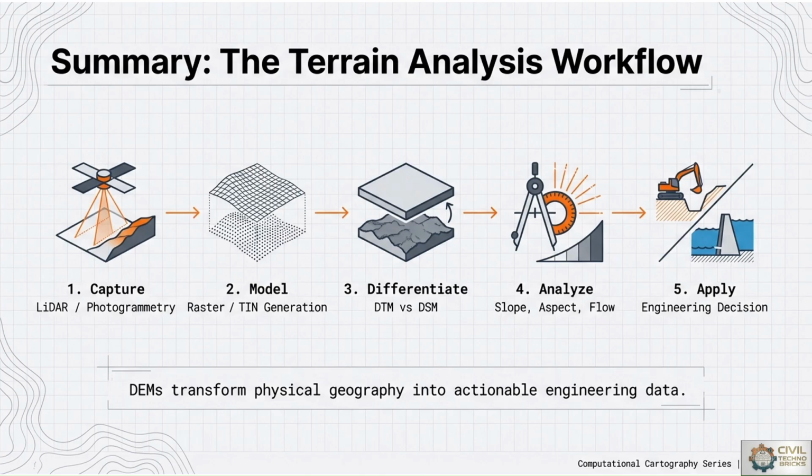The whole data is used as an input for the modeling, that is the raster data for TIN generation. The third step is the comparison of the digital surface model, digital elevation model or digital terrain model, used to differentiate the actual ground control points with reference to the elevations, the slope, the aspect or any topographical characteristics.